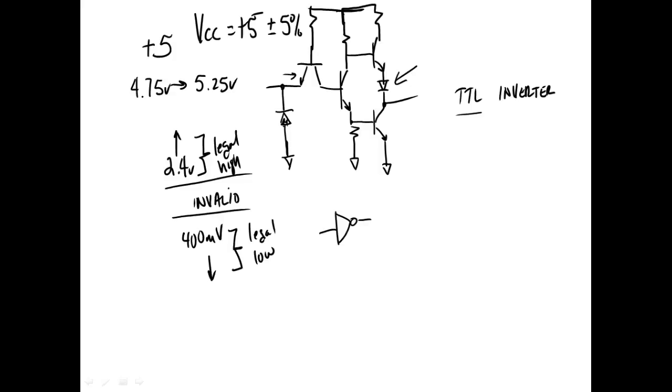Especially DC guys. So it'd be nice, and an oscilloscope is really good because the oscilloscope shows you what's there. It doesn't go through an A to D or anything like that. It shows you what's there, right? But another tool we have for very slow moving signals is something that we call a digital logic probe.